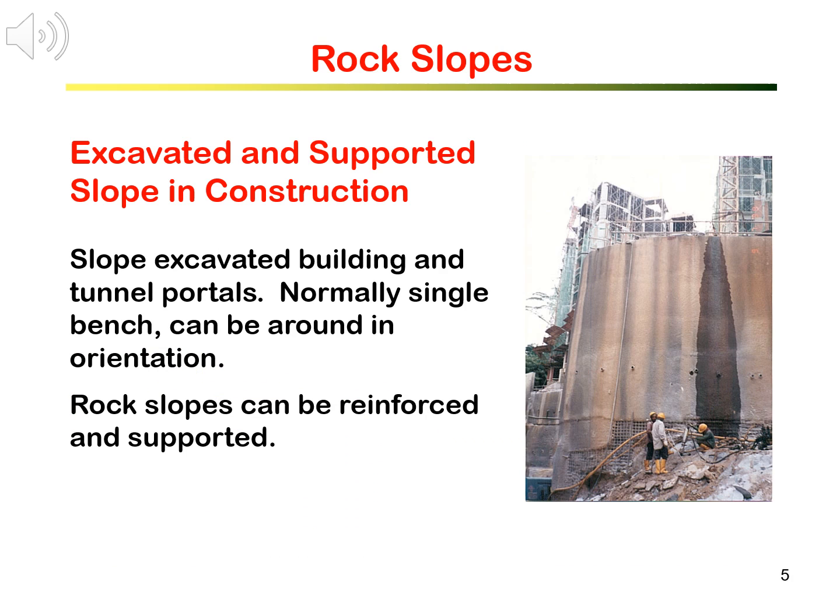Excavated slopes can also be found associated with building construction and tunnel portals. Again, they are normally single bench slopes, usually supported, as they are part of the important structures. The slopes are often around the structures and not linearly oriented, as the example shown here.